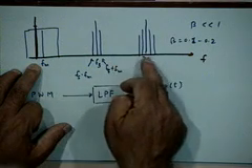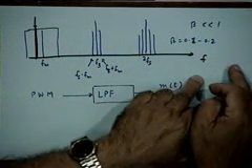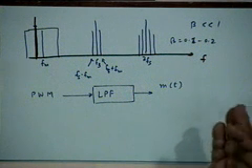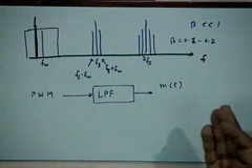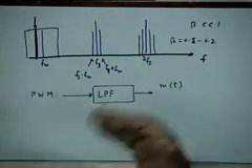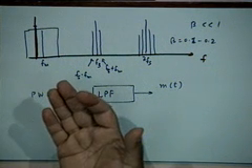The second part of the answer is that I have drawn all these pictures using rectangular pulses. In practice, we very rarely use rectangular pulses, and rectangular pulses will have this problem of bandwidth. Of course, your concern is slightly different: you have this repeated spectrum because of the sampling itself, and it blocks the whole frequency axis. But with time division multiplexing, the very fact that you agree to use pulses implies that you have sufficient bandwidth to transmit the spectrum, because that is implicit in time division multiplexing. So you can't do much about that.